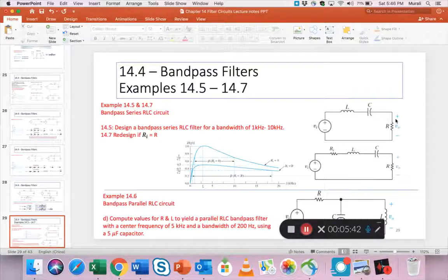So he uses the geometric mean formula, and notice that he is actually directly working in hertz. He doesn't convert that to omega radians. I think that applies in all the formulas we have studied for filters. Sometimes you absolutely have to use the omegas, particularly when you're trying to find, let's say, L or R using the definition of the center frequency or the definition of bandwidth beta.